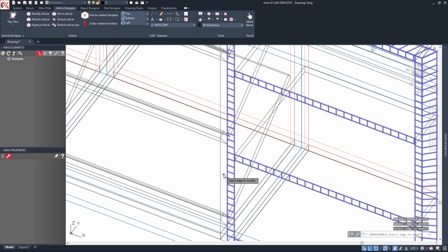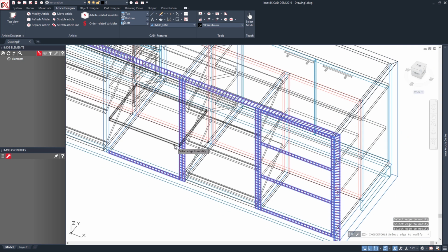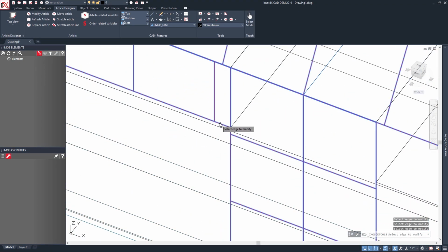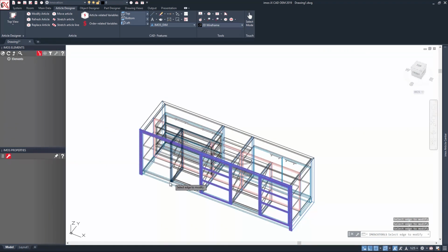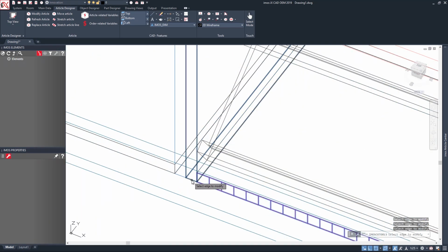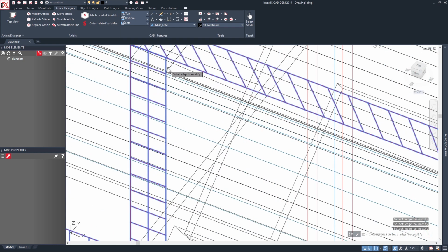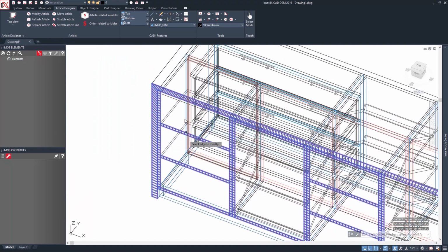Now what I won't be able to do is bring my angled shelves in line with my polyline, because that would then bend the melamine board in the wrong direction, which is no good. So I just need to omit them from the selection. So I'm just taking a little bit of time here, just going through selecting the edges that I know are going to be required for bending. So I also have this adjustable shelf, this far one. I think I'm missing one up here for my top shelf on this particular cabinet, and then one here.